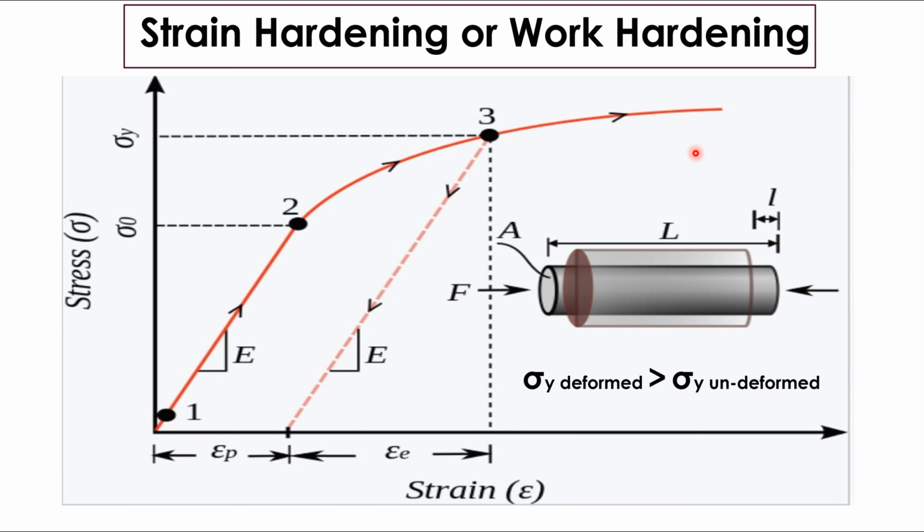It means the specimen still has some shape, but its dimensions will change, that is change in length or change in diameter or change in volume, etc. If the same specimen is used again for the test, it will show the same slope of the stress strain curve, and it will not change the modulus of the material, meaning E will remain the same.